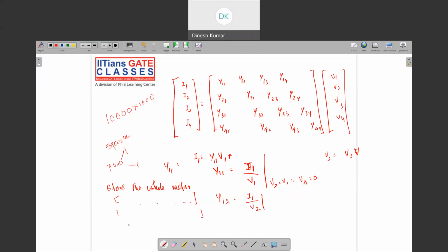So that is one of the important advantages of Y-bus. Y-bus is always a sparse matrix. But if you take the inverse of a sparse matrix, it may not be sparse. It most probably will be a full matrix, unless it is very close to identity. That means storing Z bus requires a lot of space, because we need to store all the elements in the Z bus.